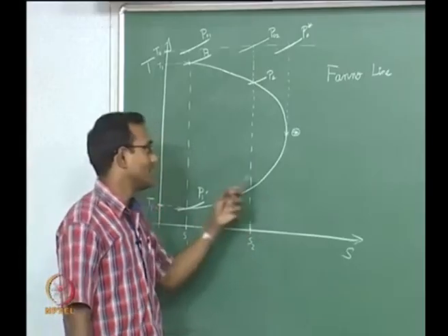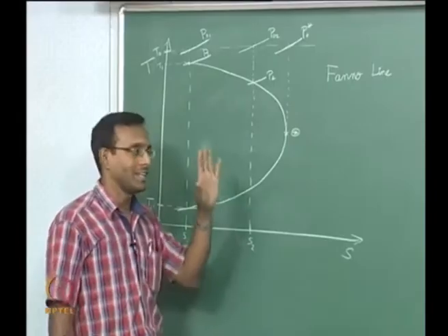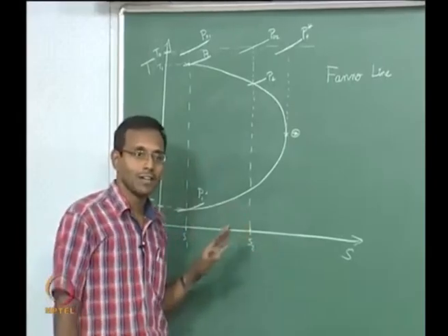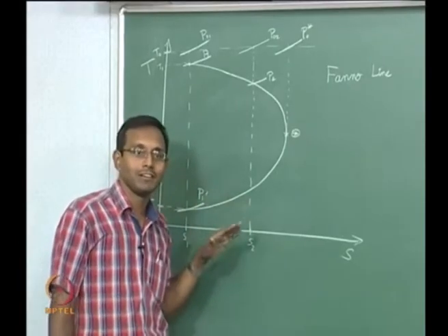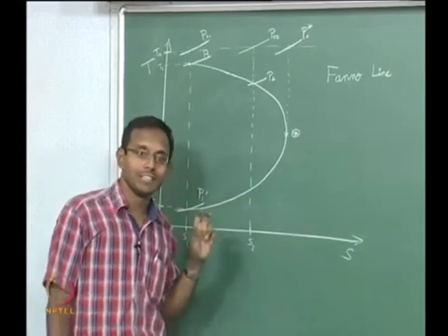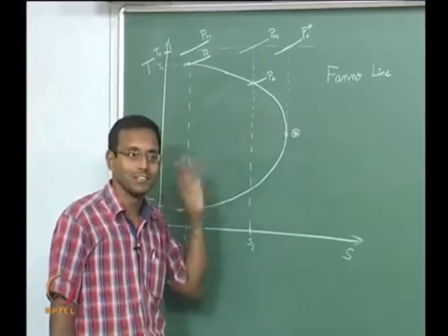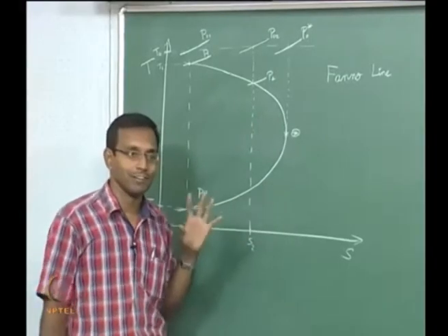So this is an unsteady phenomenon which I cannot express directly from any analysis which I have done till now. Unless I go to unsteady analysis, I cannot get that. We have assumed steady 1D. So when there is steady, I cannot go for this changing Mach number, changing the length of the duct kind of analysis.